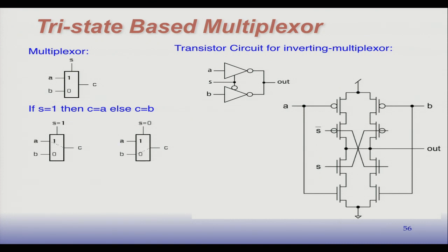And this is more transistors than the transmission gate multiplexer I showed you. But it has a nice property that it's a restoring circuit, meaning the output always comes directly from VDD or ground, not from some other circuit that's coming in on its input. Right? So it's a little easier to use, a little more robust. So this is more popular, actually. If you look in the standard cell libraries for the ASICs that we build, the multiplexers are often implemented this way.